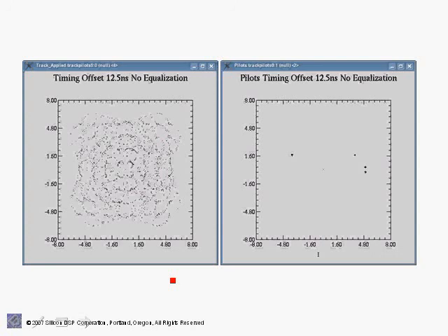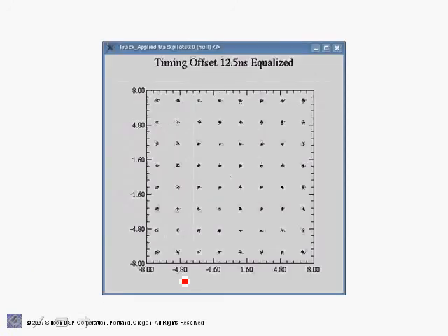However, for long packets, there's a drift due to temperature and so forth between the clock at the initial acquisition stage and as you process more and more OFDM symbols. And as that clock drifts, the pilots are used to track the additional timing error and correct for it, as we pointed out before. Here we show the actual constellation after correction for the timing offset error.